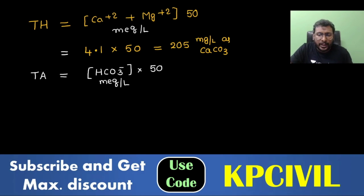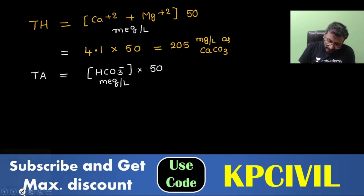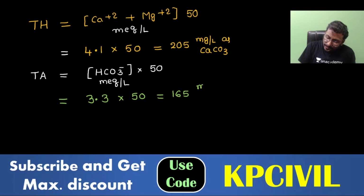If not provided, no need to consider; only bicarbonate. 3.30 is given, you will consider it. Total alkalinity is equal to 3.3 into 50, 165 mg per liter as CaCO3.